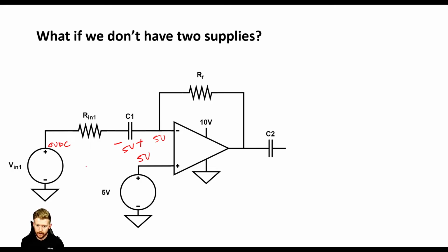And now, if we look at our AC signal, we may have our input signal of, let's say, maybe 1 volt or something like that. This is going to go through our N1, and then it's also going to get its voltage boosted by this 5 volt signal here. So we're going to have this nice 5 volt drop across this capacitor, and that actually lets this work with just a single supply. So this is like adding a DC offset to our input, okay?